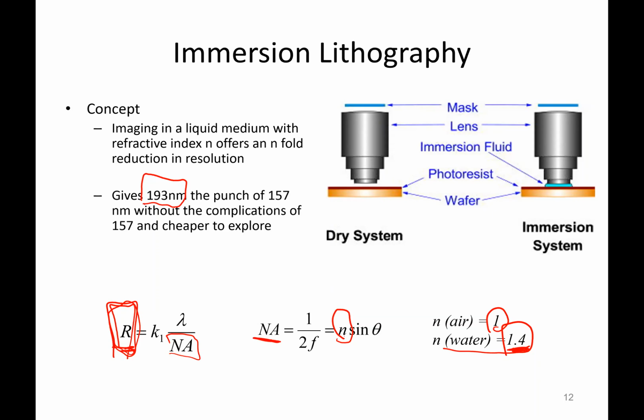So there are many different ways, but in the tapping mode case, it's pinpoint. Only that point gets the mechanical impact. You can reduce the damage instead of scratching the surface by scanning, right? And also the non-contact method is going to have minimal impact on the surface structure, right? So if you don't want to give any damage, then you choose the non-contact method.